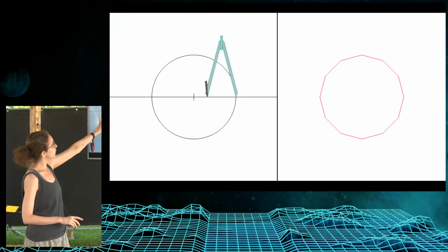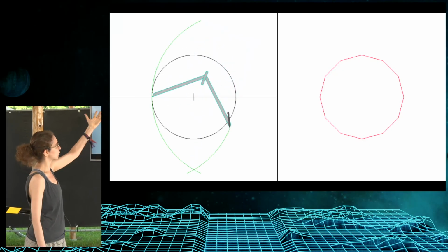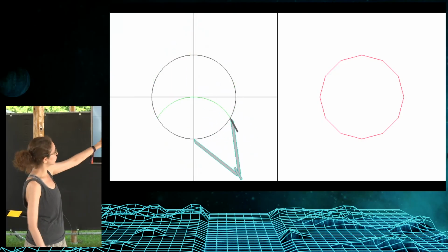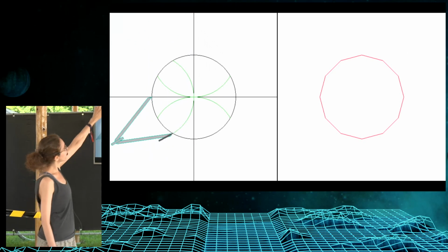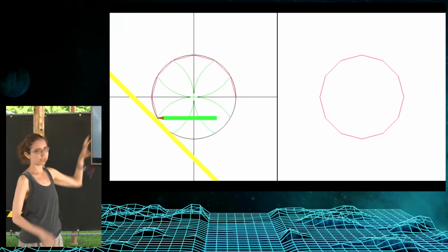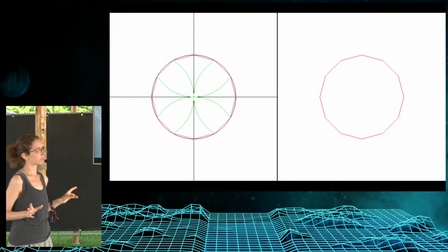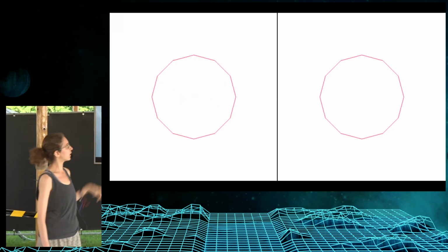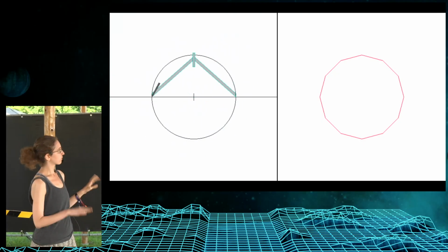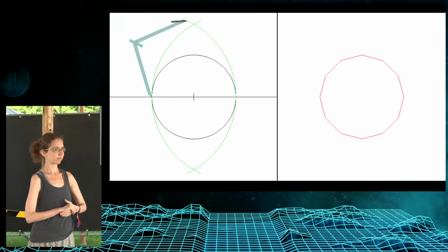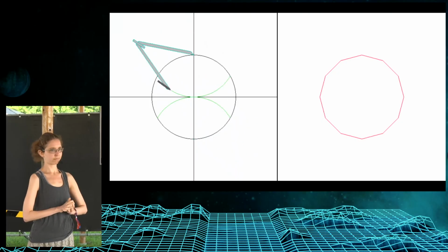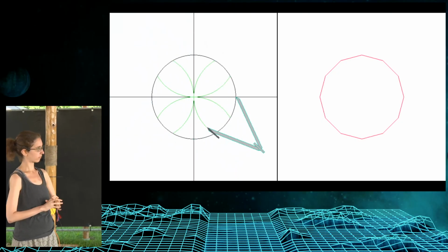So you can see here how you can do this construction. I'm not going to do it step by step, but you create a circle, then you create arcs, and then you create more arcs, and at the end you're sectioning this circle into 12 equal parts, equal arcs, and then you put the sides. Note that the auxiliary lines are removed at the end. So we have a lot of construction made to get to the actual target, right? That's an important part. We are not cheap on making lines. We need them. It's really a part of the process.